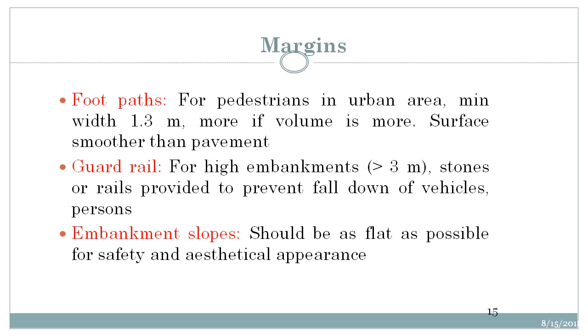Surface smoother than pavement. Guardrail, for high embankments, greater than 3 meter, stones or rails provided to prevent fall down of vehicles, persons. Embankment slopes should be as flat as possible for safety and aesthetical appearance.